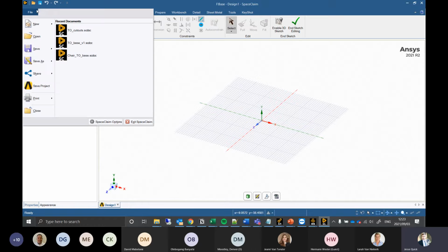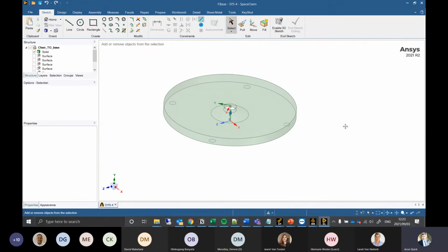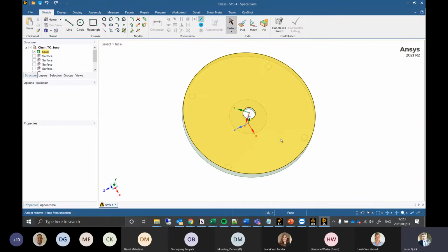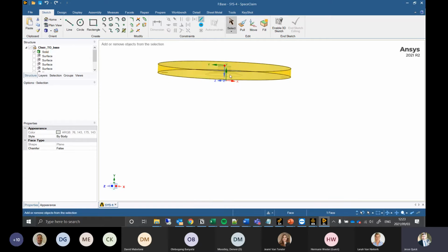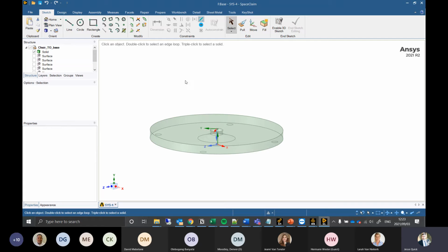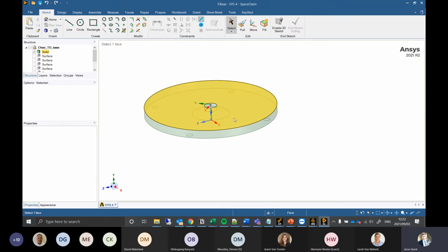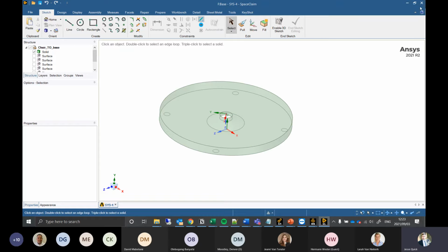So what I'm going to do now is I'm just going to go and open up, I think it's this one, the chair topology optimization base. So I've just gone and created a bulk base. So you don't want a predefined area. You want to see what the topology optimization actually gives us out of this process. So what I've got is I've got the imprints of where all of the feet are. And then I've got a solid block that I'm going to use that's going to just be aluminum alloy in this case. And we're going to go and basically eat away at this geometry to create an optimized geometry. Okay, so I'm happy with that geometry, so I'm going to just close it.